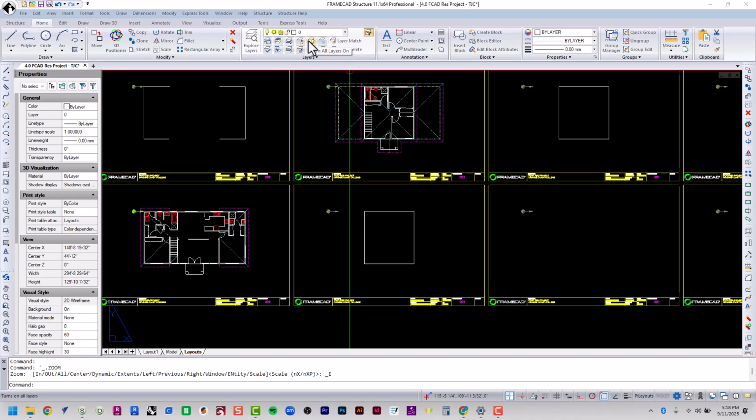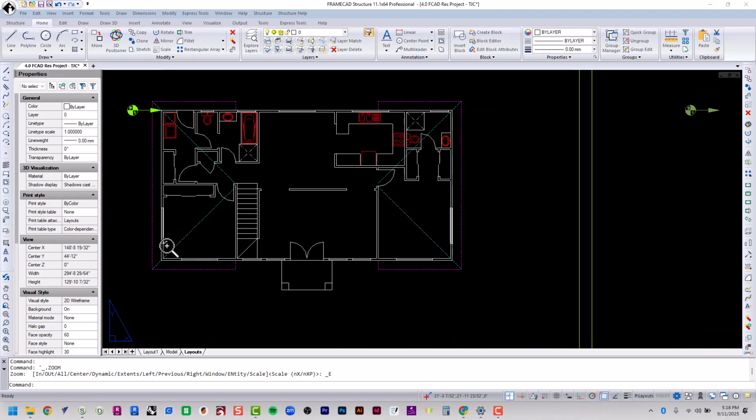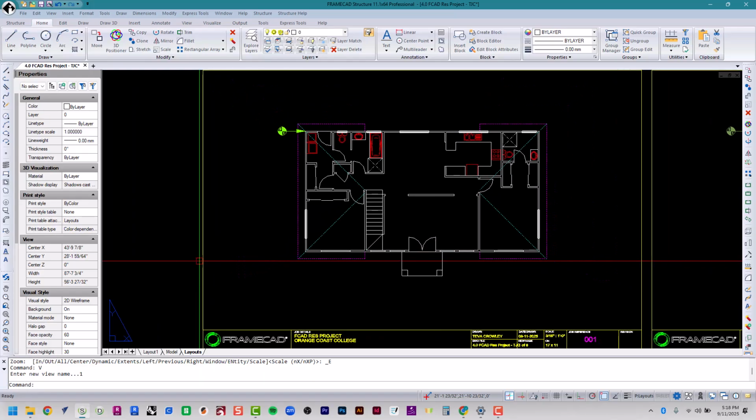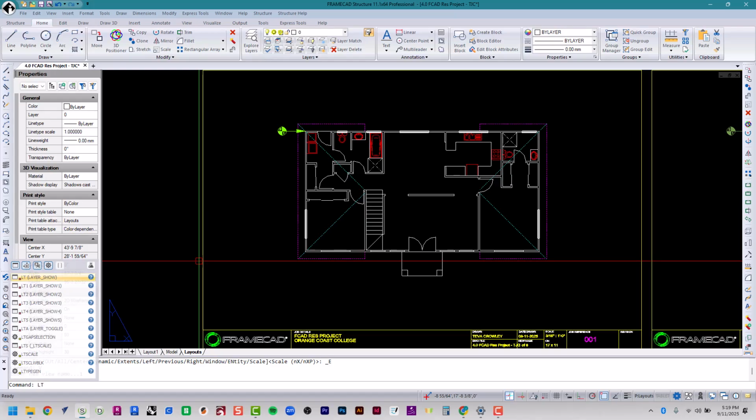In this lecture, we're going to learn how to add our interior walls and external walls too. So let's go to border number 1 by quickly navigating to it. V, enter, 1, enter. Don't forget, we have our first floor block and second floor block on temporary layers, LX1 and LX2 respectively. Let's turn off LX1 by typing in LT1.